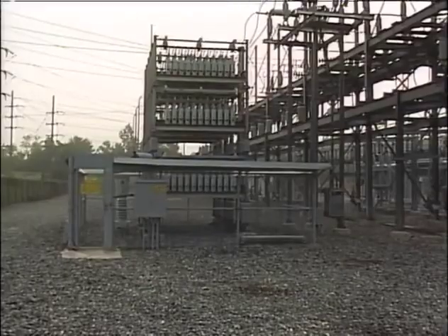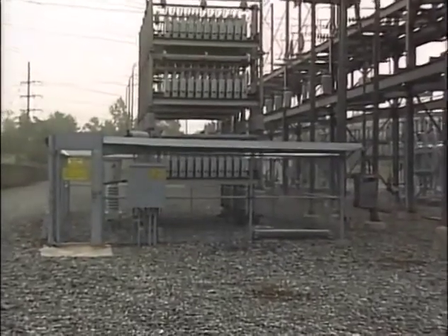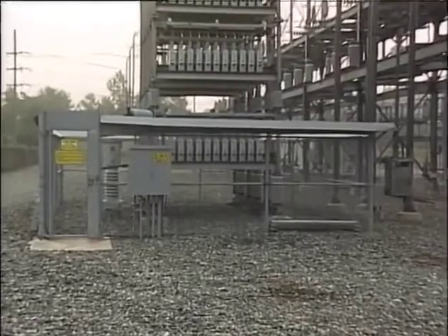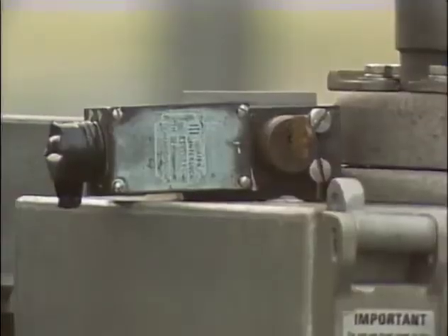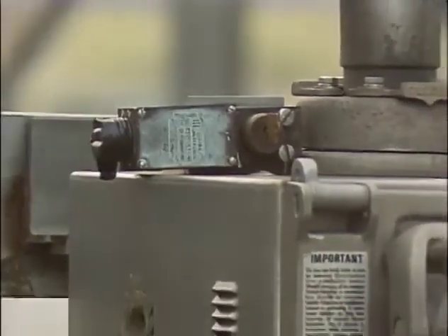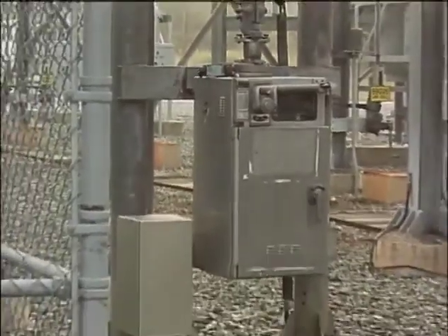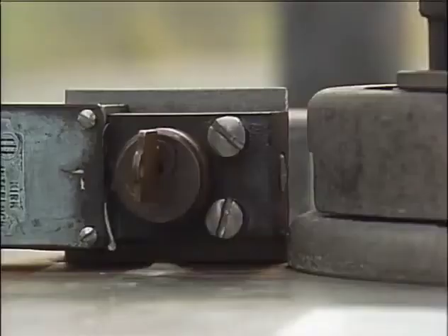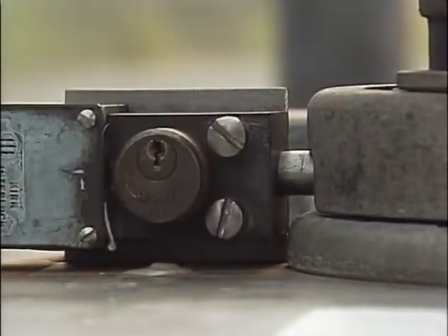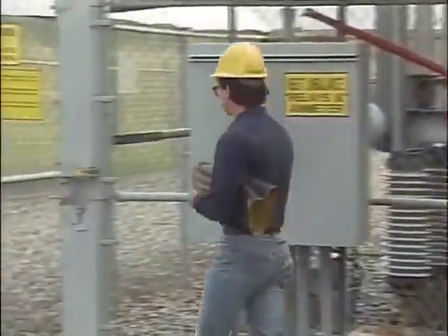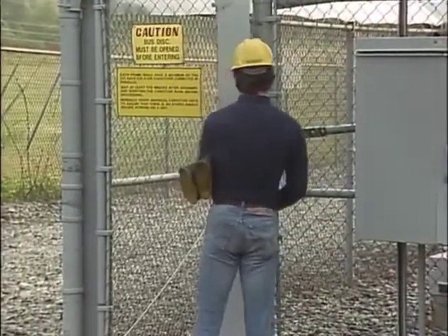In addition to the switches, this capacitor bank also has a safety interlock system. Part of the interlock system is a security fence that is normally locked. The other part is a key to the gate of the security fence. The key is normally located in the gearbox mechanism of the switch that isolates the capacitor bank. The key cannot be removed from the gearbox mechanism until the switch is opened. This helps to ensure that the capacitor bank is de-energized and isolated before the gate can be opened.